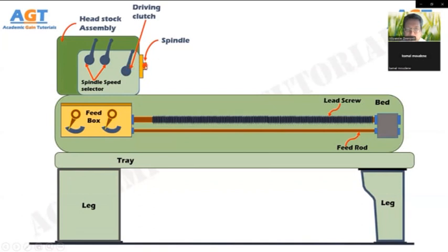Here, this is the spindle connected to the headstock. The spindle possesses a live center to which the workpiece can be attached. There is a hole throughout the spindle for handling a long bar of workpiece. The spindle is hollow inside, and has threads cut on the external surface. On the other hand, the chuck has threads cut on the internal diameter.